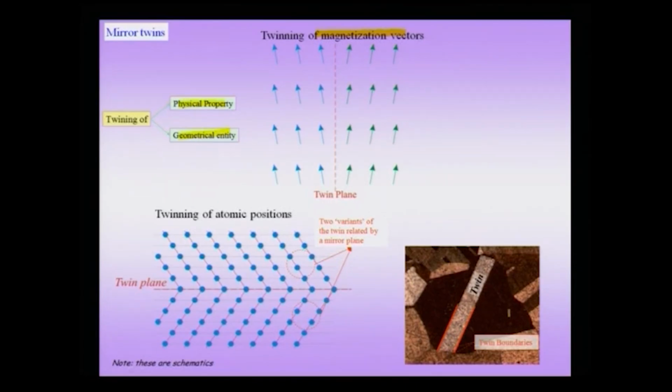The sample here is actually annealed copper, and in annealed copper you find these straight lines which can be seen here. For instance, these two lines which are marked in red are actually the twin boundaries. So, let me extend this straight line to show you where the twin boundaries are, and as you can see, their signature is that they are extremely straight. There are other twin boundaries right here in the same picture, this is another twin boundary, and these twin boundaries reside within a grain. Now, what happens at this twin boundary?